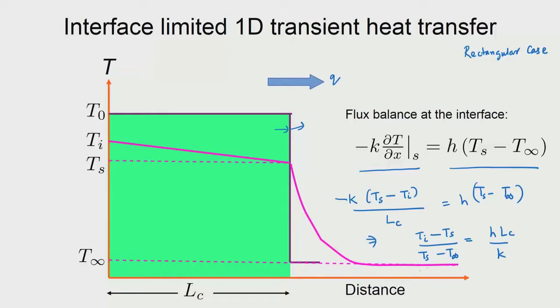Now, if you look at the left hand side, this is telling you how the temperature differences inside the bulk are related to the temperature differences outside. The outside temperature difference is given by this, and the inside difference is given by this. So, what happens if this is small? What does it imply? It implies that the temperature gradients inside the bulk can be neglected, which means this quantity could be of some importance. You can see from the left hand side that there are no units, which means that on the right hand side also there are no units.